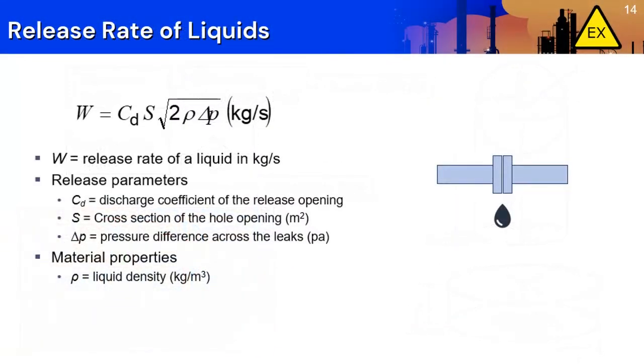The IEC standard incorporates a formula for predicting the release rate of a liquid. The formula is not very helpful in determining the degree and extent of a classified area because, as we have discussed, it's the size of the pool that is more important. The formula may be helpful in estimating the size of a liquid pool for assessment. It's important to be realistic about the pool size you use for assessment. It should depend on the interval between routine inspections and the size of the containment.